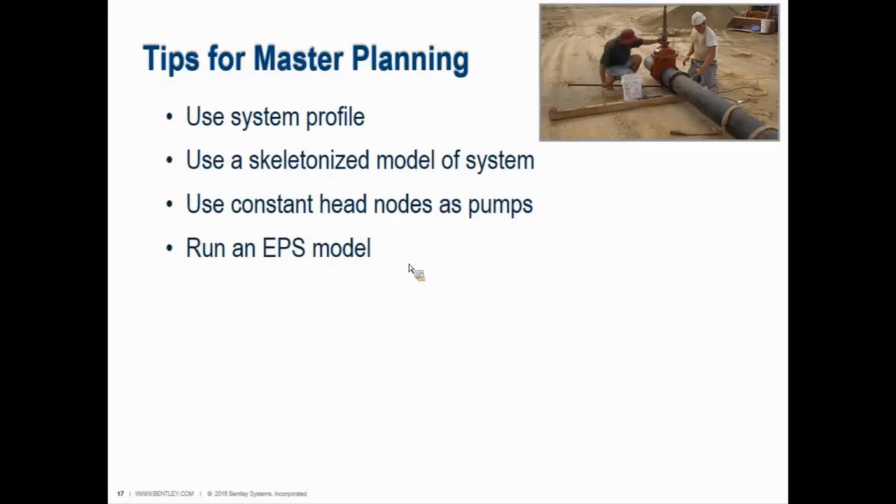And maybe in master planning, you're trying to make sure that, as lake water levels change throughout the season, the pump station head is going to be enough to get it where it needs to go because of the net positive suction head coming from the reservoir or something. So you can make these pretty grand designs at the master planning level, but the more skeletonized the model that you're dealing with, the easier it is to do that because you have fewer things to change.